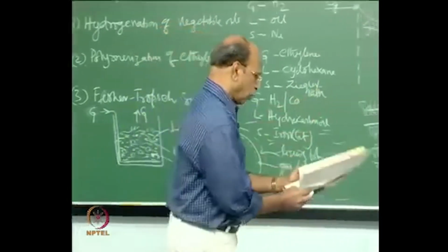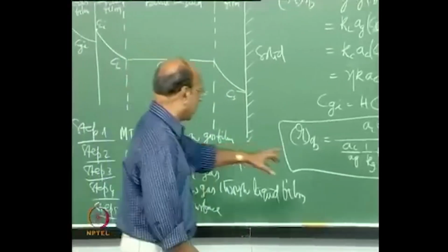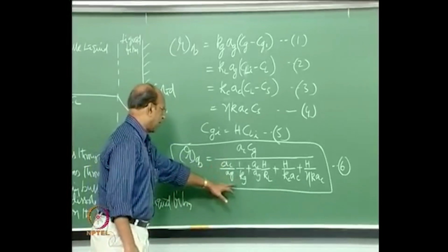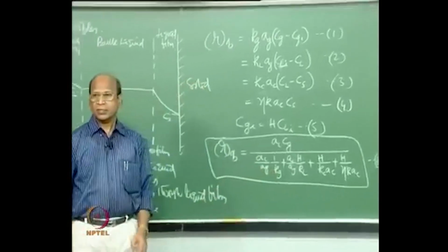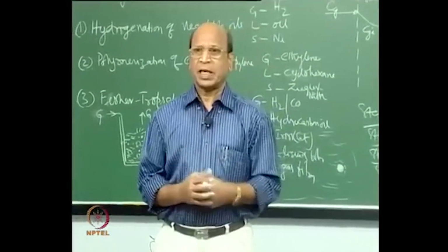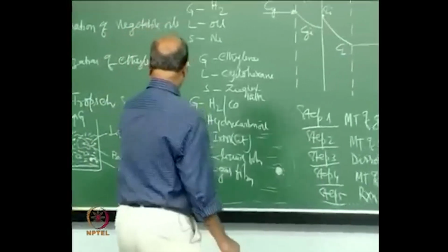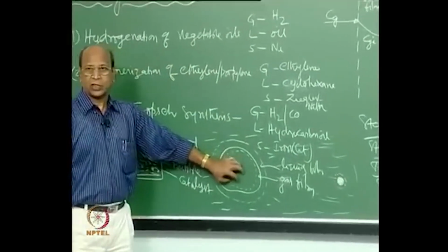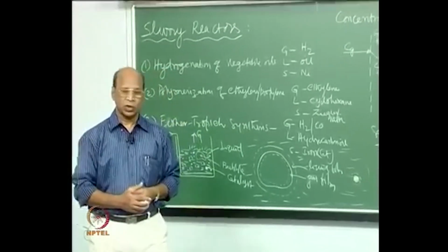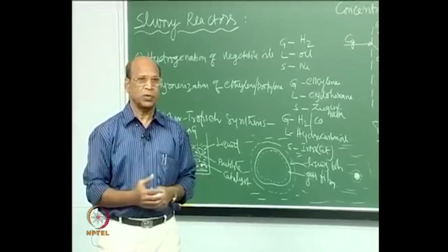Okay, good. So now quickly we will try to find out how do you... there is another thing here. Even though there are some correlations for Kg, most of the time it is not at all rate controlling, because it will be much faster, since gas diffusion is the easiest one. In the bubble I have, let us say, two gases, hydrogen plus some other gas. Hydrogen can happily go without any problem, whatever gas you put there, because that is the lightest. Diffusion is very easy for that.